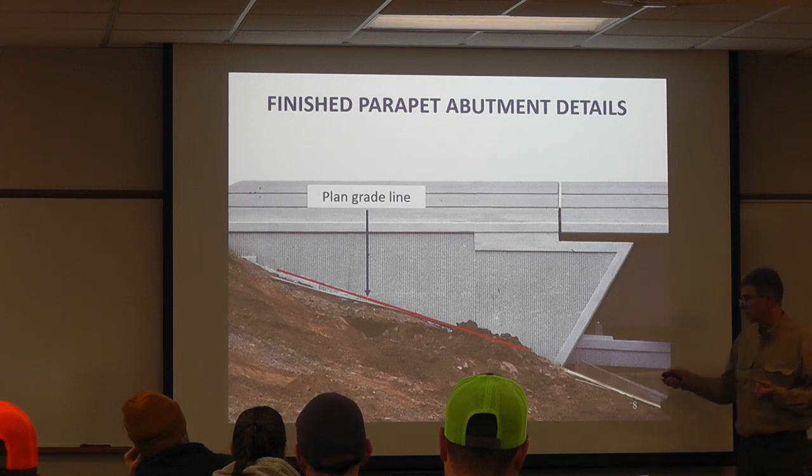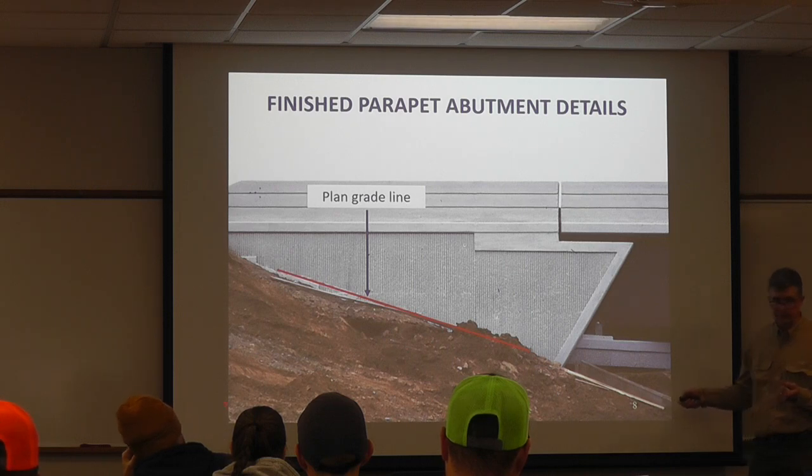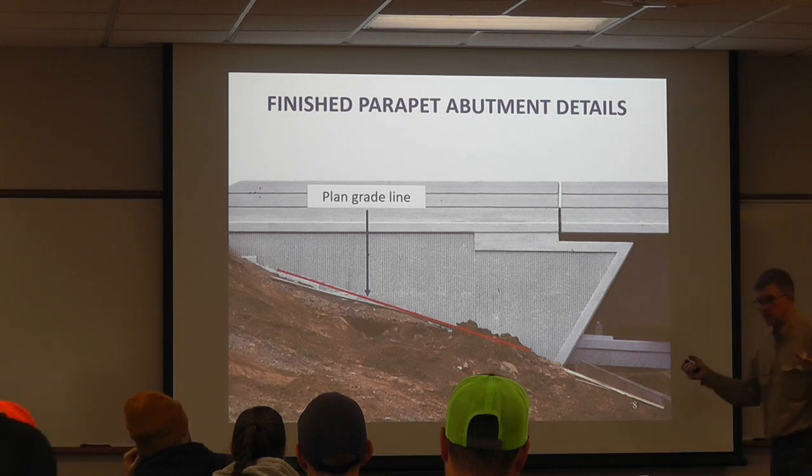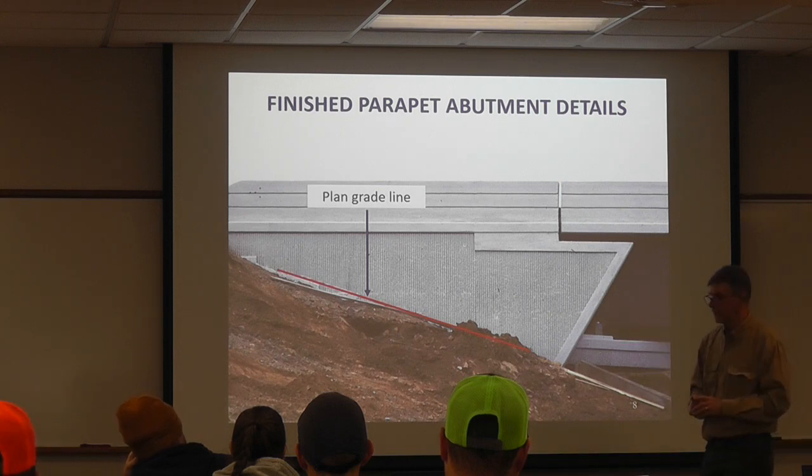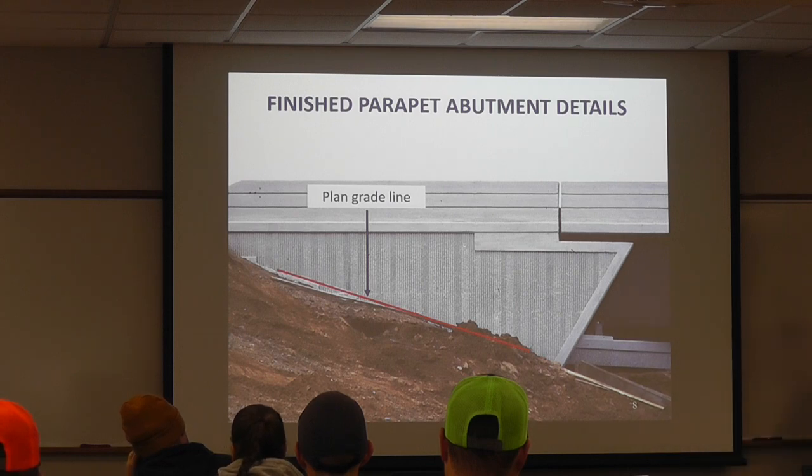And I think as we mentioned the other day, we always want at least 4.5 feet of cover from our grade line to the bottom of the footing. So that's just Minnesota frost will go down 4+ feet at times, and so that is what we have. So that's the grade line.